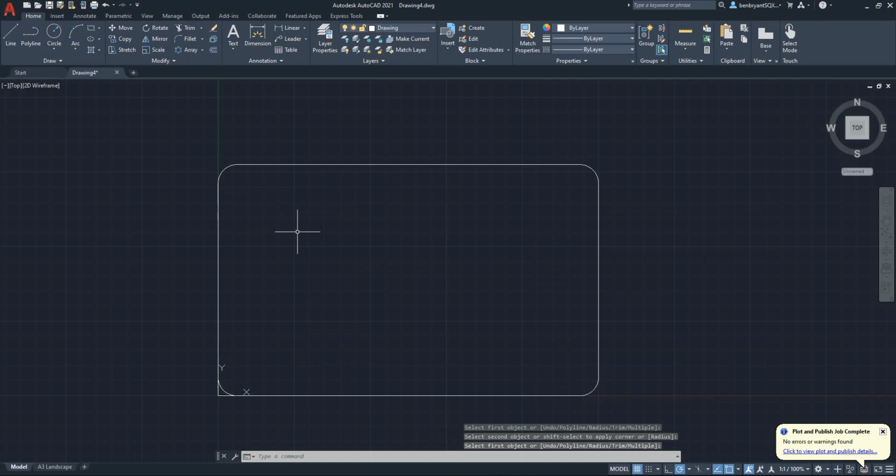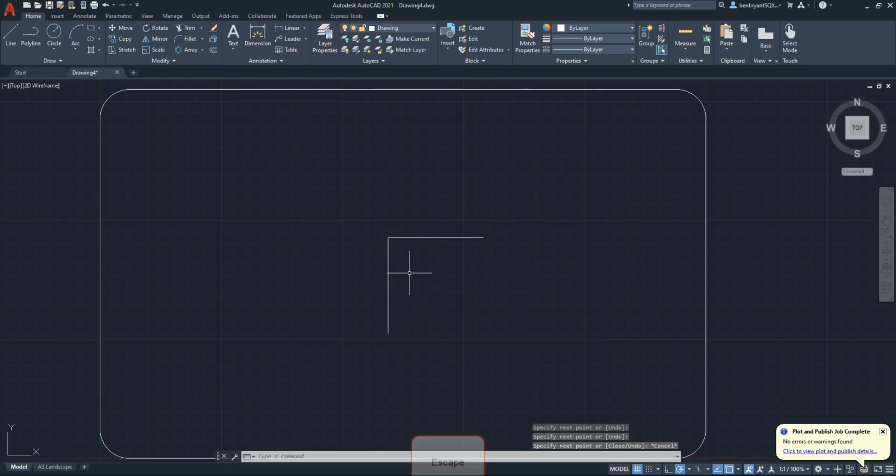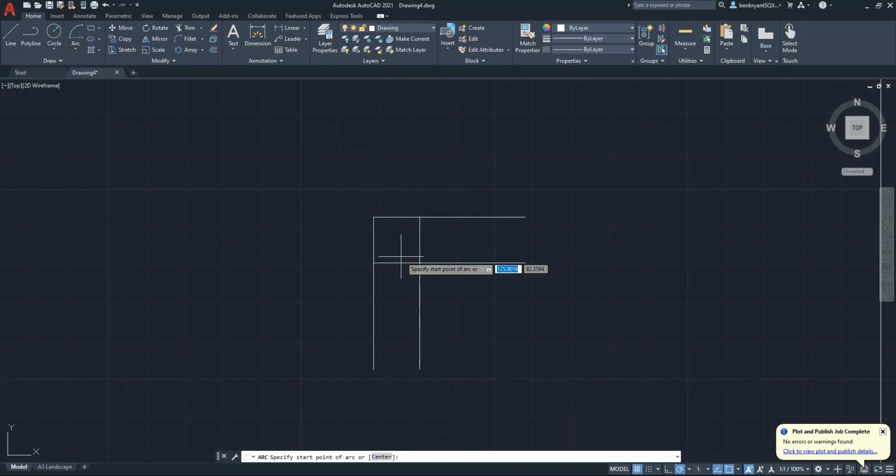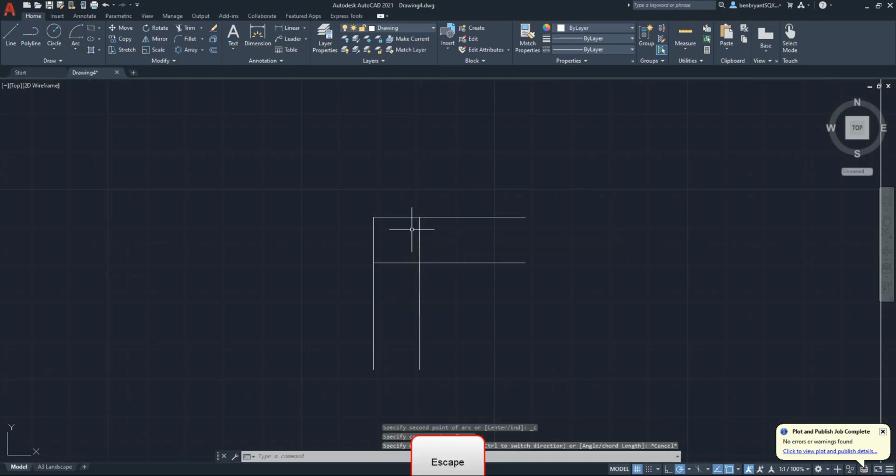Another way to do a fillet would be to draw 2 points, like that, and then put a circle in or an arc and trim it, but you need to know that it's 12. So you'd be drawing a line. I could show you: you could do offset 12 up, 12 across, and essentially you could use start center end, so start center point, and then you come around it and you have to locate the end point. That tool needs to start from the top, like so. It's not a very good way because you have to make sure you've got all your orientation right.